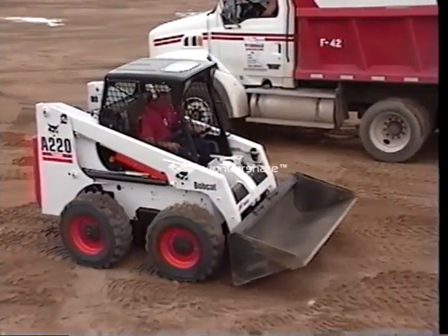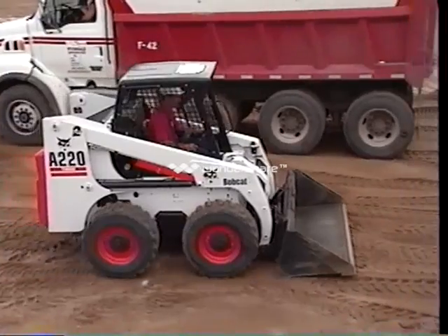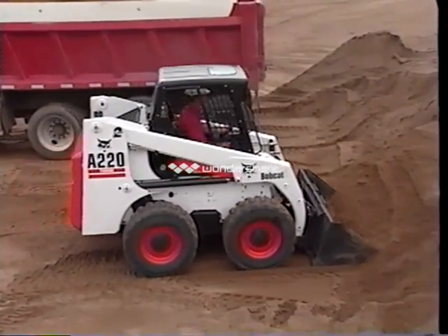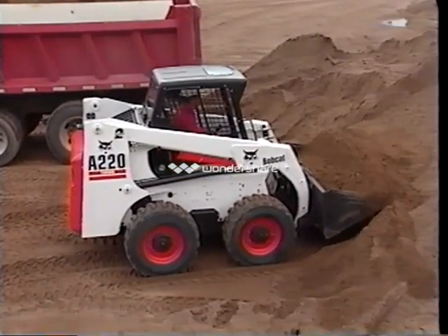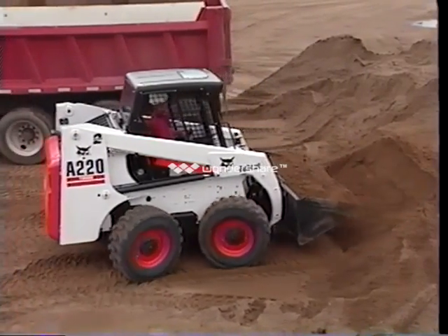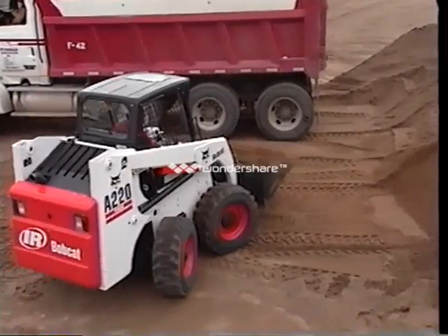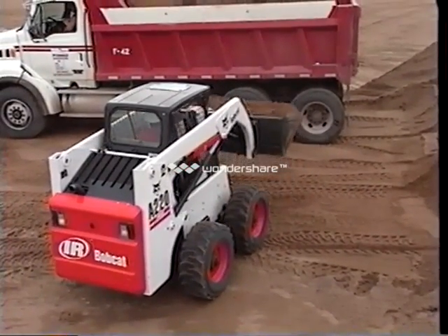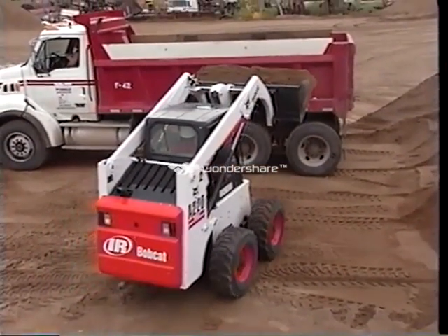Remember, moving the left joystick smoothly is the best way to operate the loader in either steering mode. You are working with a hydrostatic transmission. The loader will react the moment you move the joystick control. The further the joystick is moved from the neutral position, the faster the loader will go.